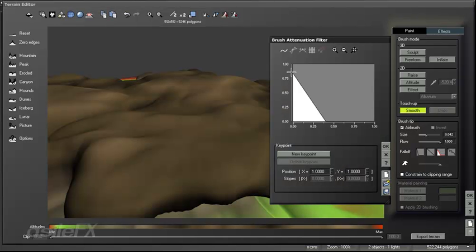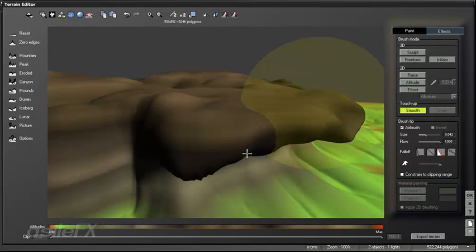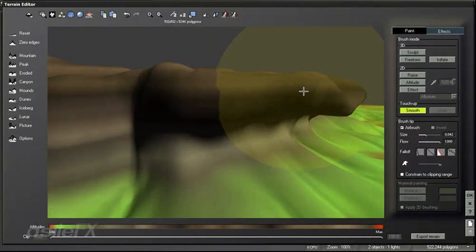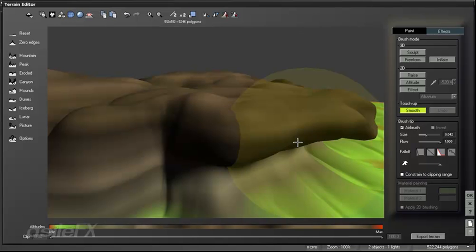I'm going to go ahead and edit this filter and just pull up this left point to 1, and I am going to take this over to 0.5 and just bring it slightly over. Hopefully that will prevent the geometry from doing what it just did, where it got really jagged. Because if you're editing just that outer or lower geometry layer and not modifying something smaller, it could cause a few issues.